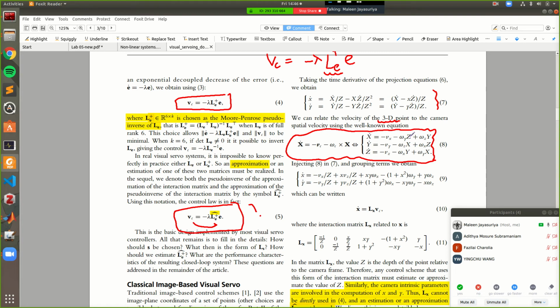So if you look here, you can see that rotations and linear velocities are related to each other in this way, right? So this is a relationship between 3D velocities and 3D points. Here we have the relationship between the 3D point velocities and the 2D velocities. So combining all of this, you can get a nice relationship between the 3D velocities and the 2D velocities, right? Which is ultimately what you want, right? Here you have the 3D velocities and the 2D feature velocities here, right?